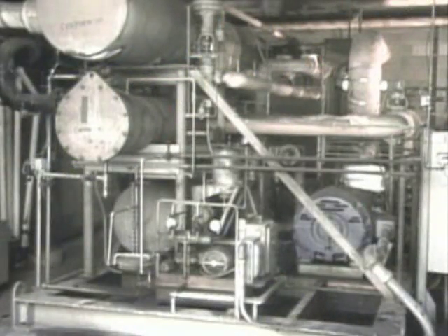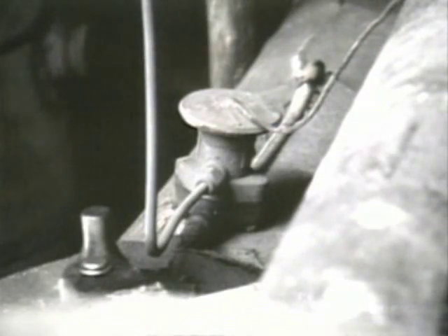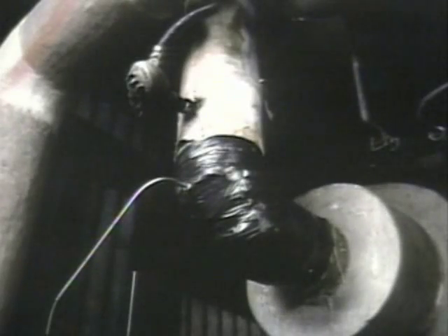In many systems, refrigerant flow, and therefore the amount of cooling, is controlled by an expansion valve. The position of the expansion valve is controlled by the temperature of the substance being cooled. Some control systems use a thermostat located in the area being cooled to position the expansion valve. Other systems may use a thermal bulb or a thermocouple.